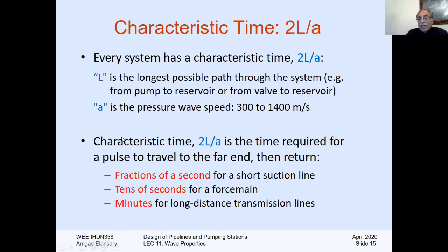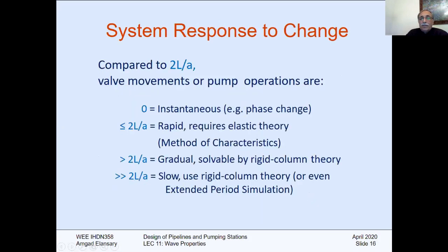Sometimes it's a fraction of a second. If it is a short suction line, for example, it will be a tenth of a second. For a force main, or it will be a minute for a long distance transmission line. Okay, every category here has a different attitude and different handling of water hammer.